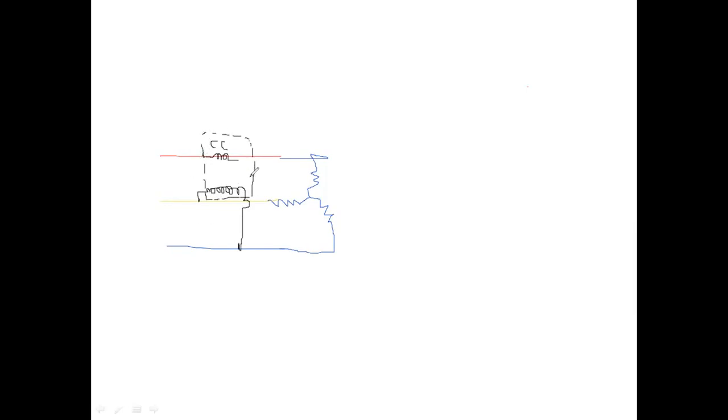So in this way, whatever the wattmeter shows is the reactive power, and as this is three phase, we can find it from the reading. Say the wattmeter reading is W1. Then the reactive power is Q equal to, as this is three phase, we have to multiply with root 3 into W1. This is the reactive power measurement of the three phase.